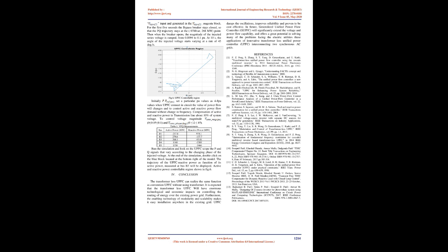UPFC damps the oscillations, improves reliability, and is proven to be cost-effective. In future, the Generalized Unified Power Flow Controller, GUPFC, will significantly extend the voltage and power flow capability, and offers a great potential in solving many of the problems facing the electric utilities. These are applications of the innovative transformer-less unified power flow controller, UPFC, interconnecting two synchronous AC grids.